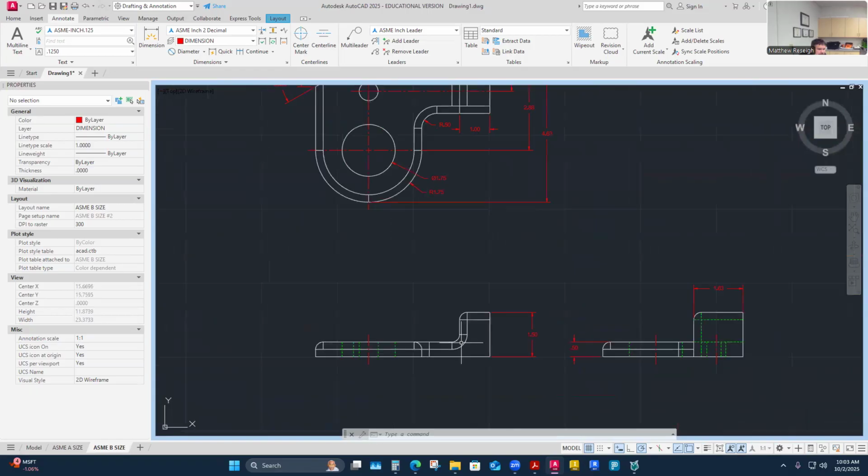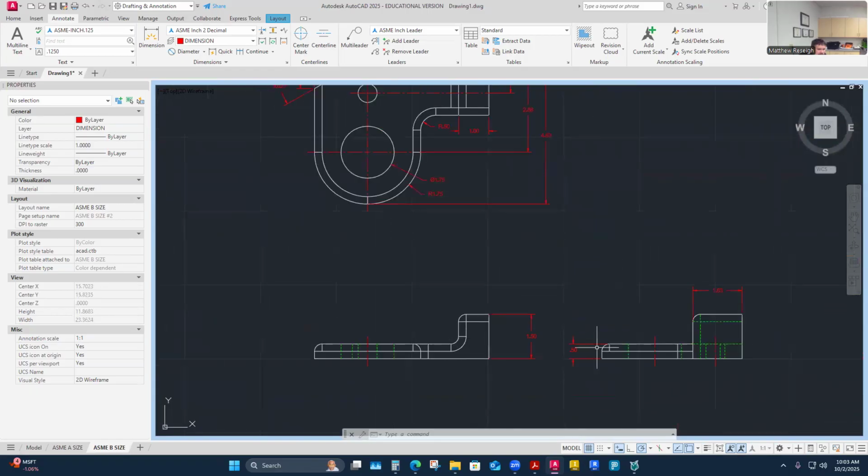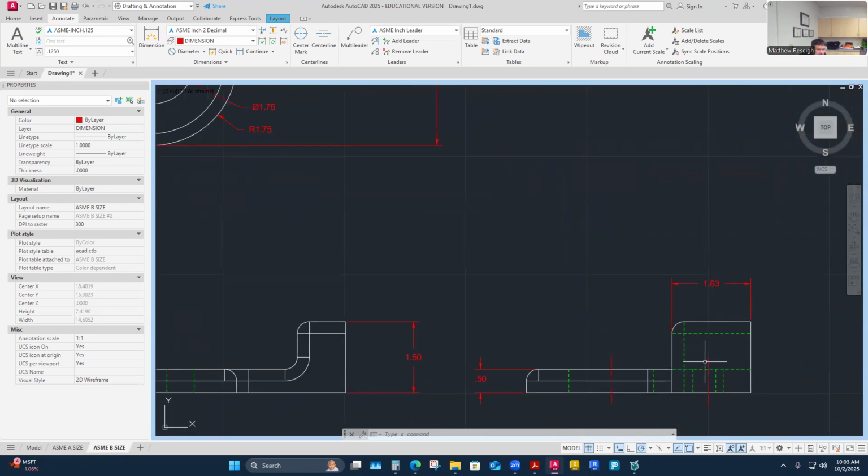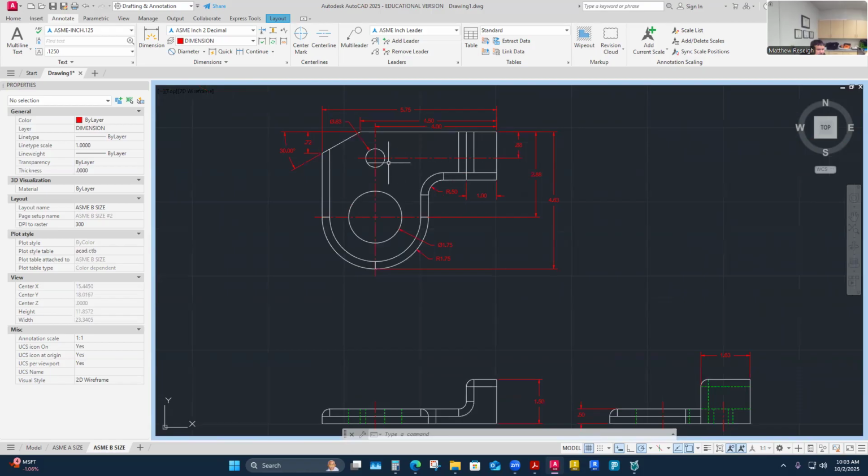I have few dimensions going on down here just by the nature of it. But some of these I probably could pull here to the hole location. That would be the 0.88 as well. I don't need to put it in here because I got it up there, but I could have put it here and I think that would be fine. It's just that you're only going to get one of the location dimensions in this view, right? You're only going to get that 0.88. You're not going to get the other one from this surface that's towards me out to it the other way. But that's okay. It just makes your viewer reading your print have to know that there's the whole size, and then there's one of the locations, and I'd have to come down here and see that this is the other location. And that's okay. That's good practice.